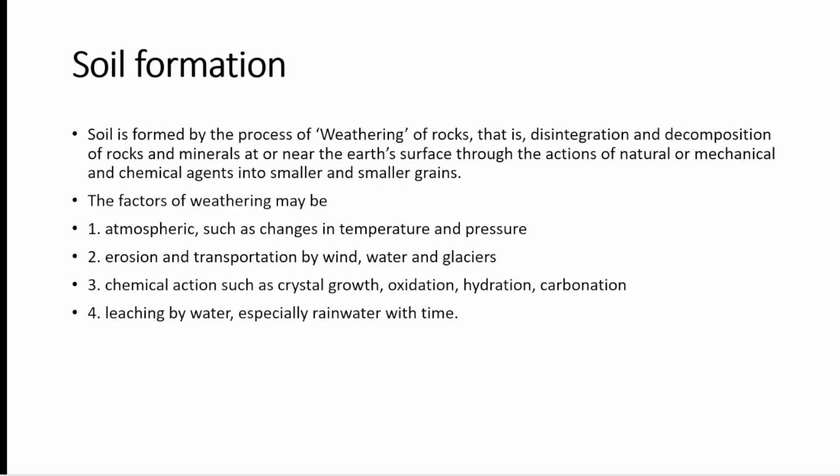The factors of weathering may be atmospheric, such as changes in temperature and pressure, erosion and transportation by wind, water and glaciers, chemical action such as crystal growth, oxidation, hydration, carbonation and leaching by water, especially rainwater, with time. Obviously, soils formed by mechanical weathering, that is, the disintegration of rocks by the action of wind, water and glaciers, bear a similarity in certain properties to the minerals in the parent rock, since chemical changes which could destroy their identity do not take place.